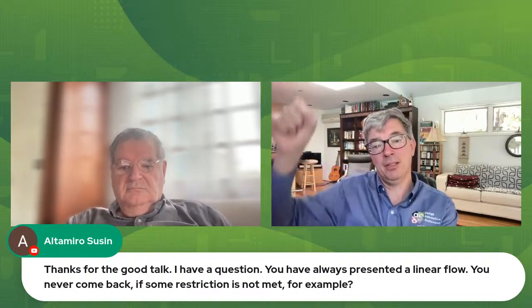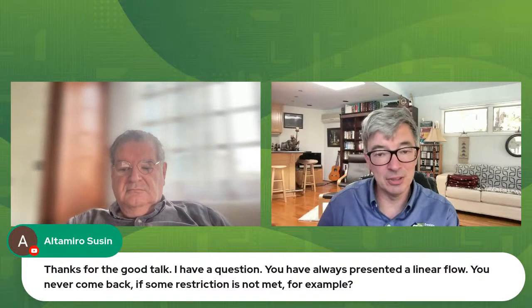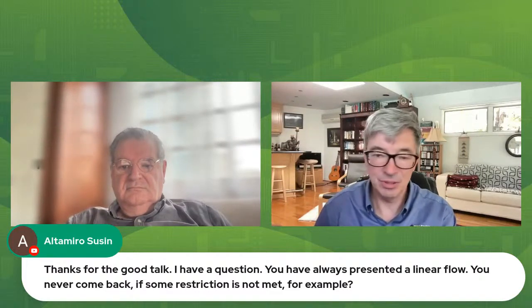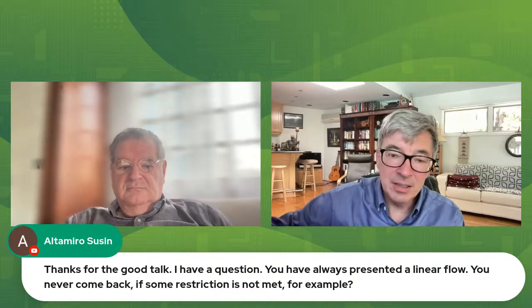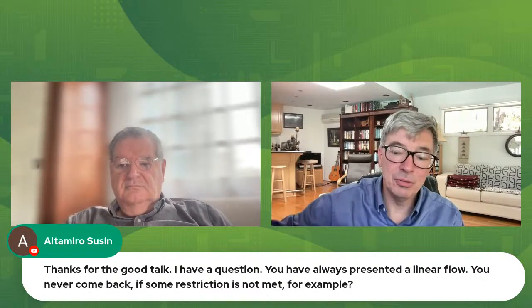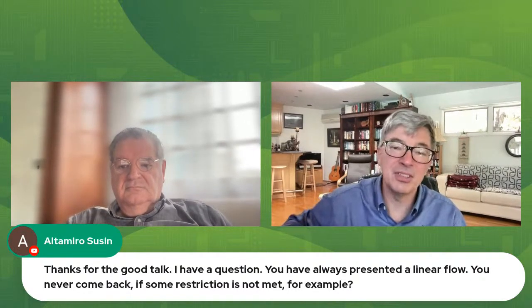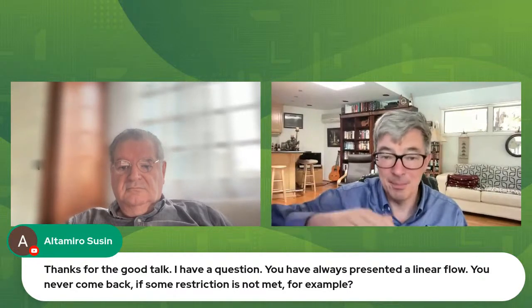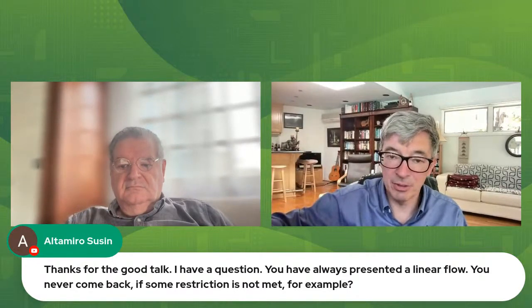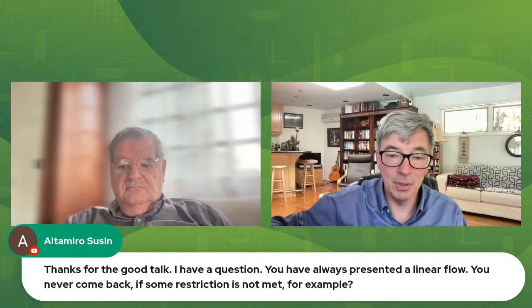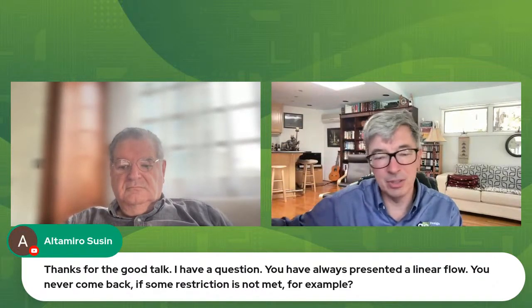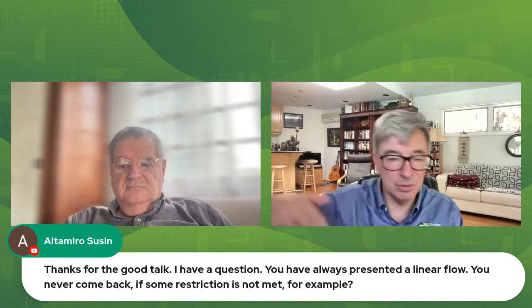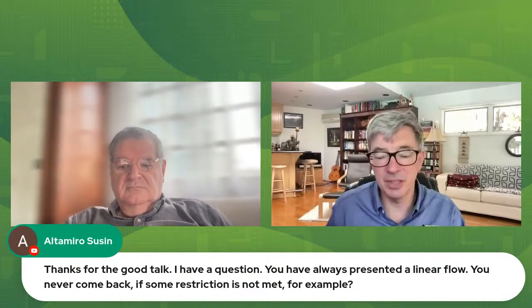But at the big picture, it's a linear flow. And at a certain moment, you look at the results, you say, not so good, I need to improve that. What we see now happening with both tools from Cadence and Synopsys is this task: I run through this linear flow, I don't like the results, what do I do to improve it? Then you would look at some reports and you would tweak a little bit your RTL or move the placement or whatever, do a few things.